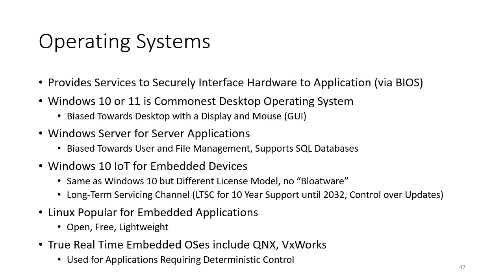So for example, they've maybe got better memory protection, they've got things like watchdogs to prevent routines from running too long, and there may also be specific ways of handling interrupts to make sure that things can happen in a true deterministic manner within a predetermined amount of time. Whereas you might not get that with Linux or Windows 10. They might execute an interrupt, but there might be some delay before the interrupt actually happens, and that delay might be variable depending on what else the computer's doing. So if you want a true real-time application, you'll probably be using one of these real-time operating systems.